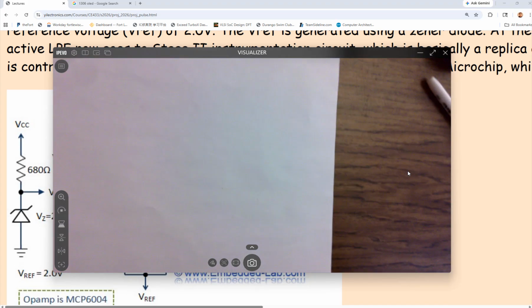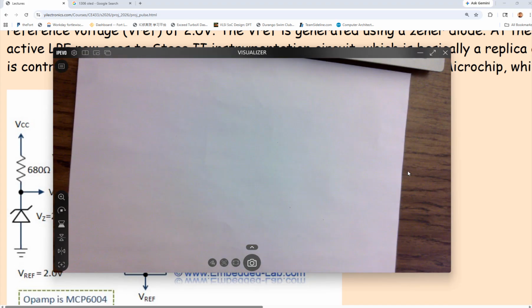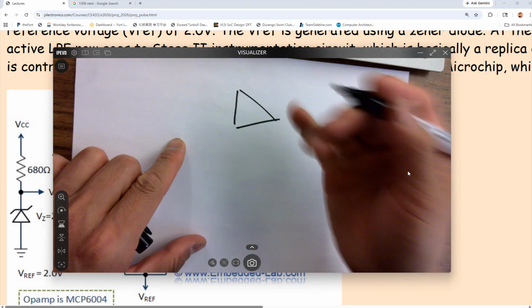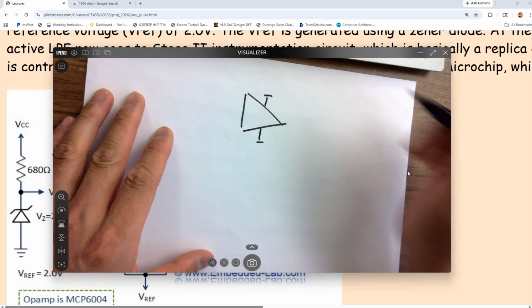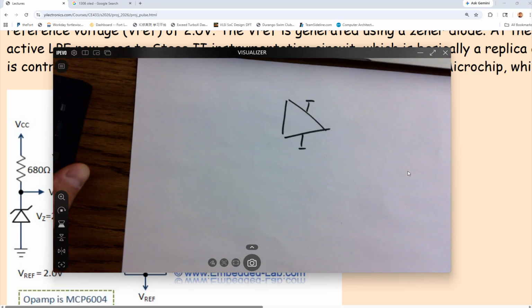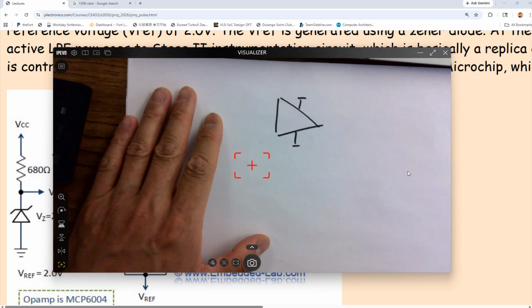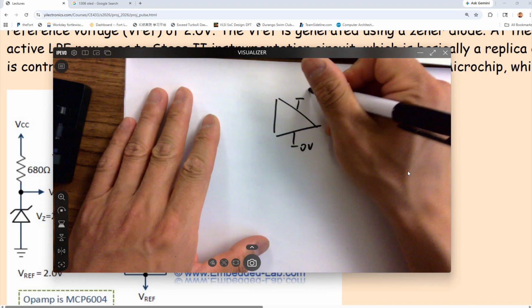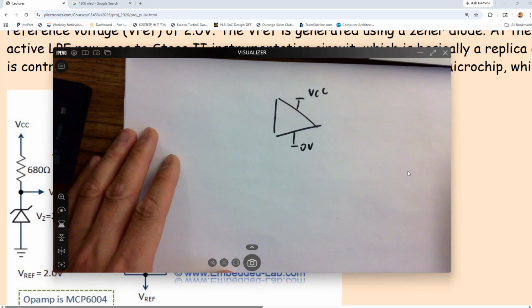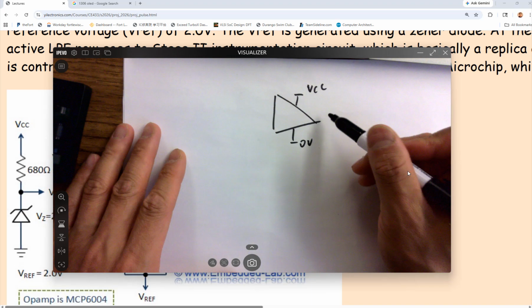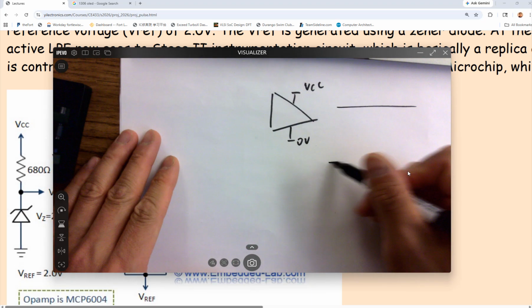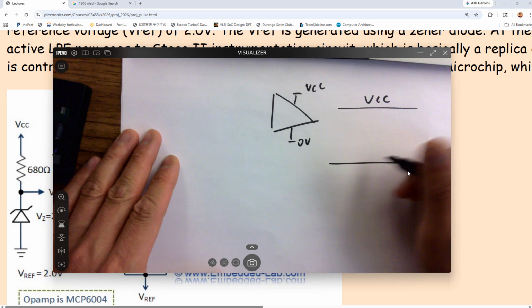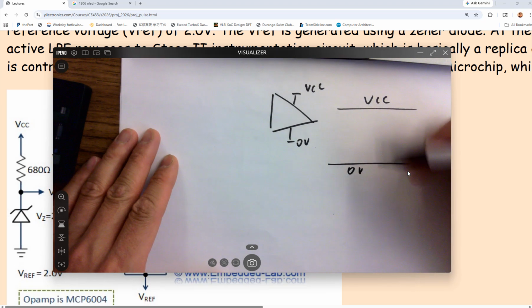Which is bad, right? So your op-amp, in circuit 1, we did a dual power supply, but in the real world, we very rarely do that. So it's usually either ground and VCC, right? So that's for two rails. And if you have these two rails from 0 to VCC, that's going to be the range of voltages to swing, right? So it's going to be in this range.